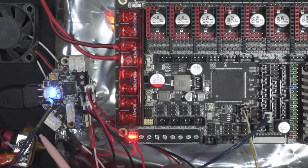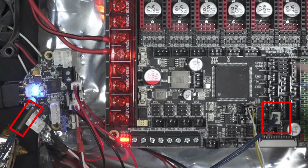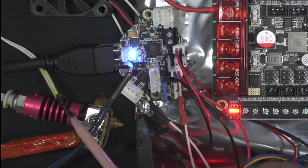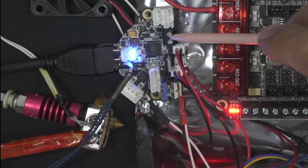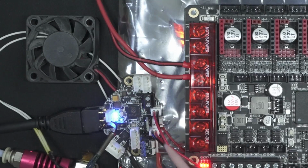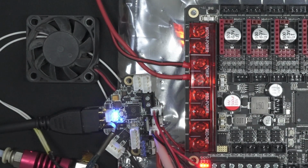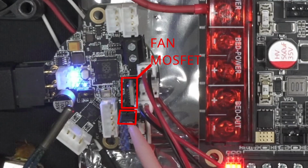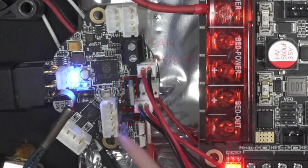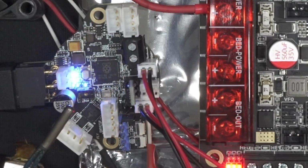Now I have connected the thermistors. This is the ATC thermistor, which is connected to the main board on the THB port over here. Then on this hotend, there is an NTC thermistor, which is connected to the toolhead board on this particular port. This is a 24-volt fan, which is connected to the FAN0 port over here, and I have also installed this jumper on the header pins, the very first one, which is for VCC. So now we'll go to Klipper and see the configuration, and then we'll check the temperature sensor and the fan.